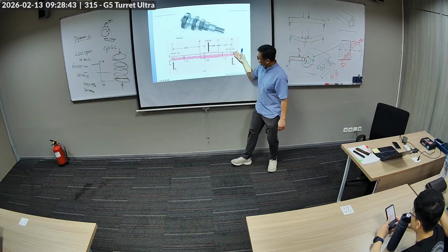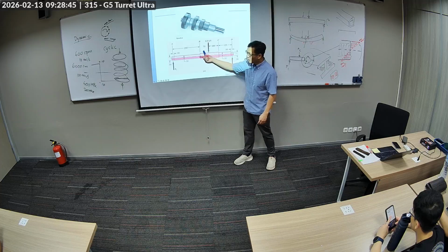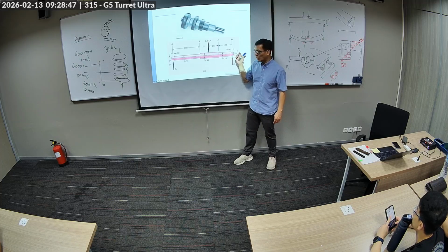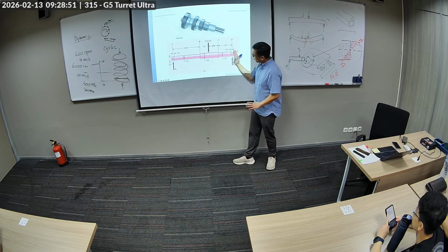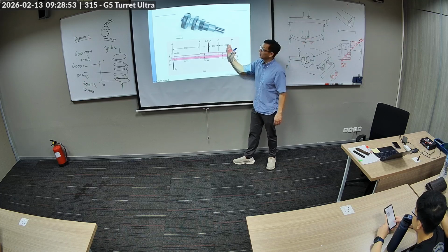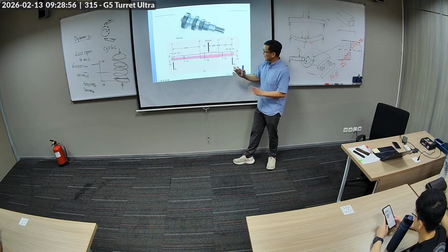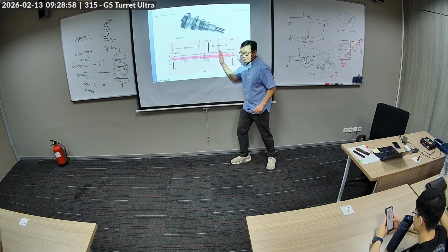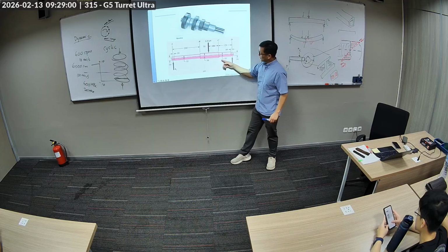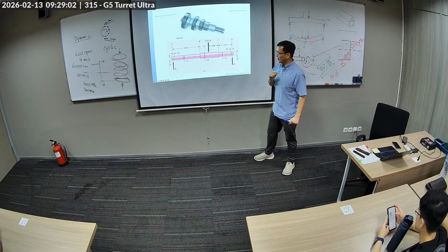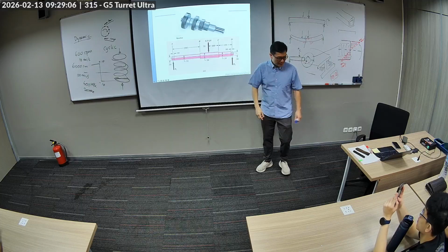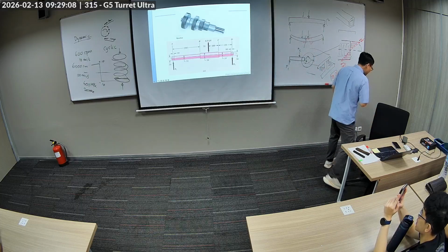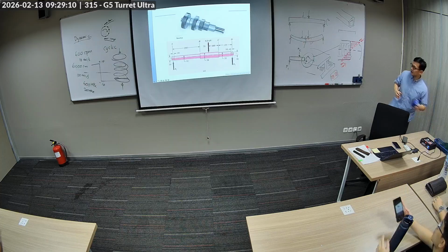And besides, if you make it straight, it's going to be weakest in the middle. So oftentimes you make it bigger in the middle, but it also is for positioning bearings, gears, etc. And so you push it until it stops. Okay? And that's the location for the gear. Now, because of this step, you have what is called a stress concentration.